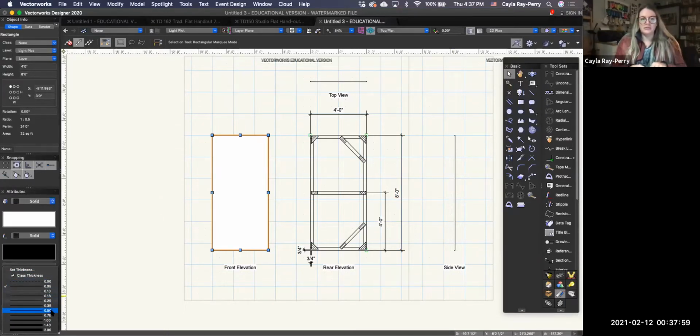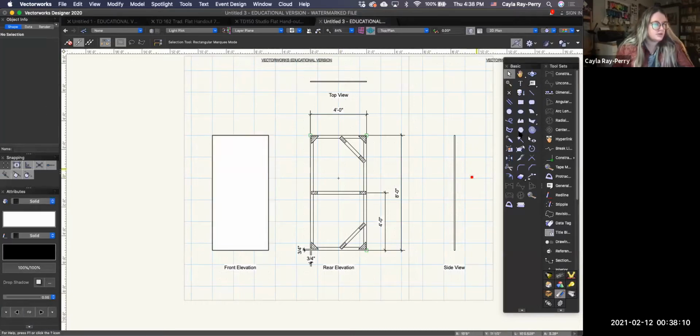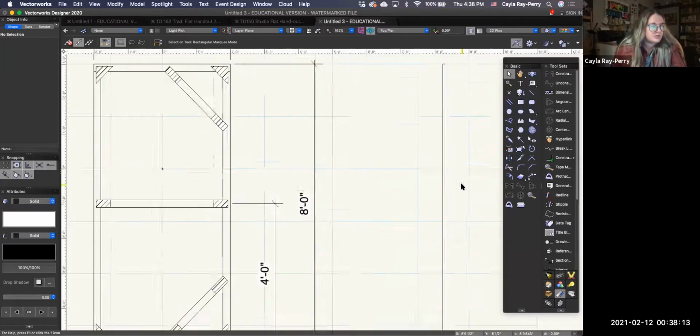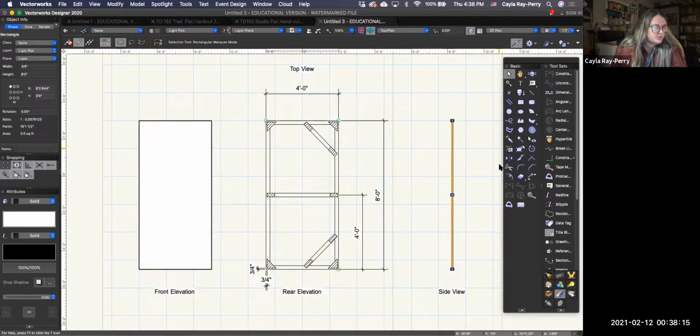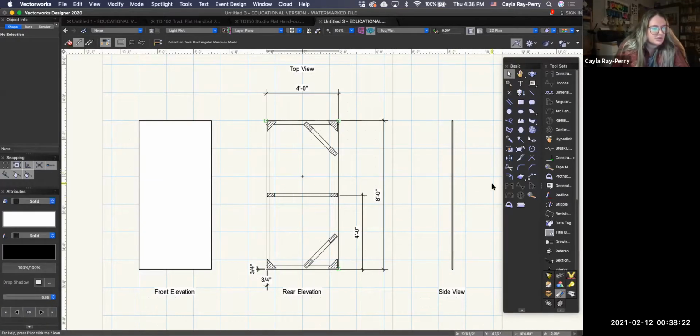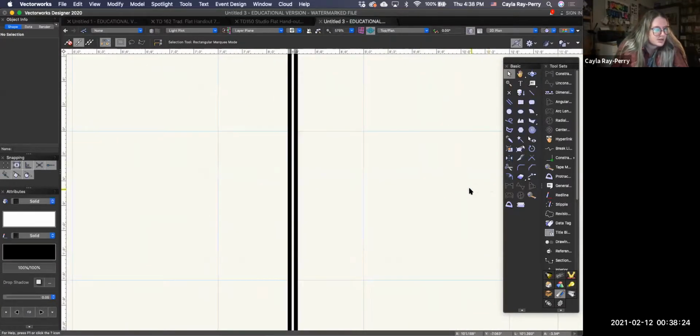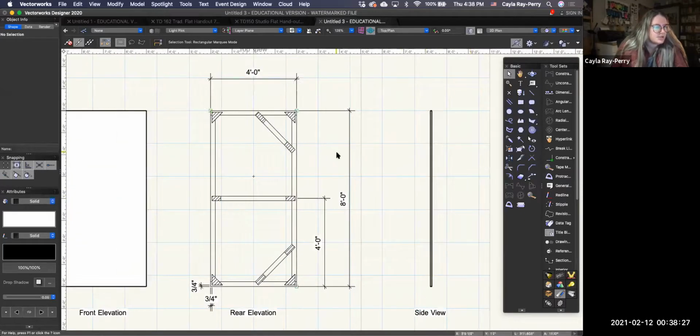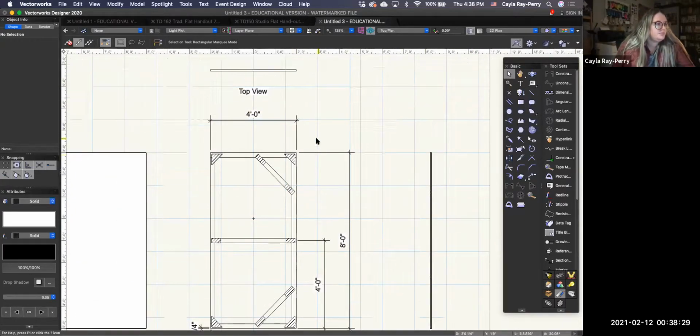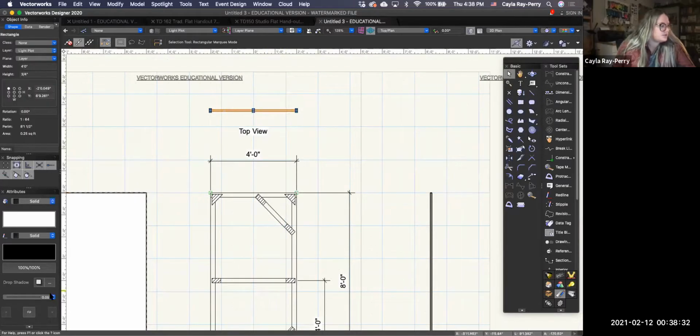An overall outline should be one of the thickest points. So this is an overall outline. I'm going to call it 0.5. This is an overall, so I'm also going to call it 0.5, although it's so small that it's hard to see. We'll see what it looks like when I render it. And this is an overall outline, so I'm going to also call it 0.5.